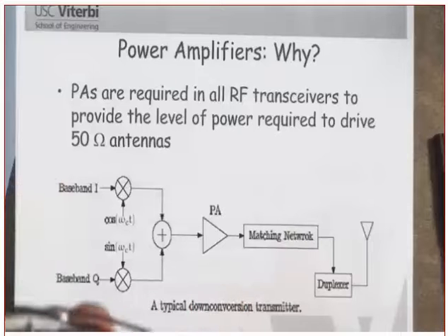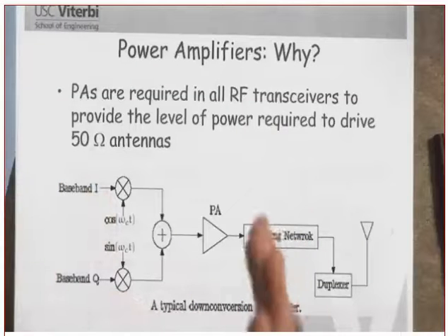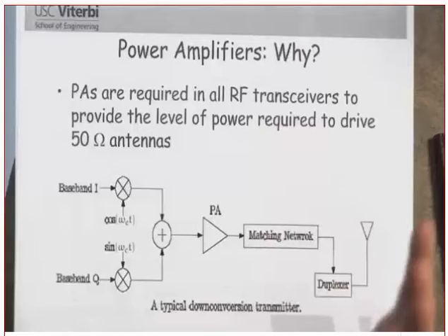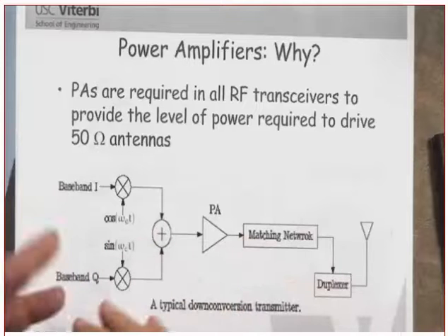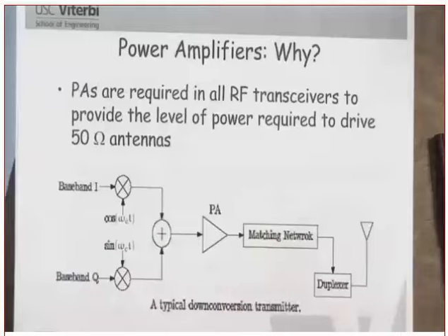What does preserving the integrity of the modulation mean? It means that we need to make sure that the modulation we are using is confined within the transmitted bandwidth. Do you understand it or not? We don't want to introduce distortion, whether it's AM distortion or PM distortion and so on. So phase modulation or AM modulation distortion. Did you get this or not?